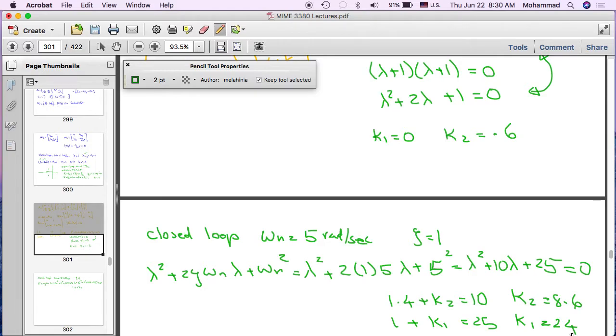So if you have MATLAB open, please create a state space model with the A, B, C, and D matrices that we found for the open loop. And then first simulate the open loop, so give it a step input. Because the open loop is underdamped, it should show oscillation. What we want to show is that by proper control, you can actually stop that oscillation.